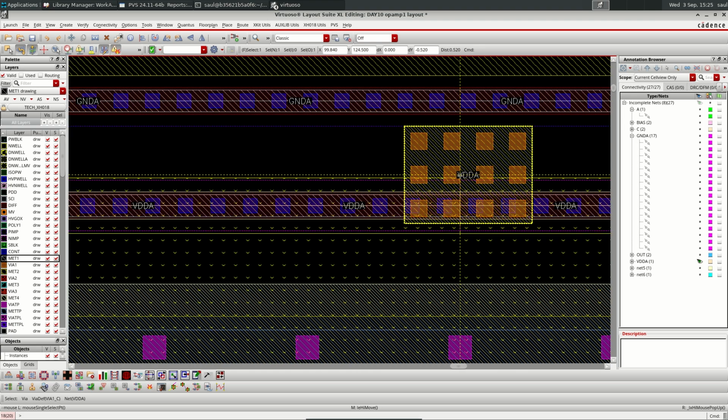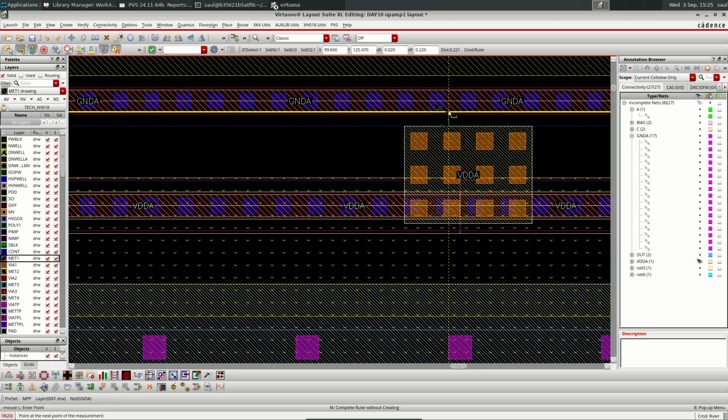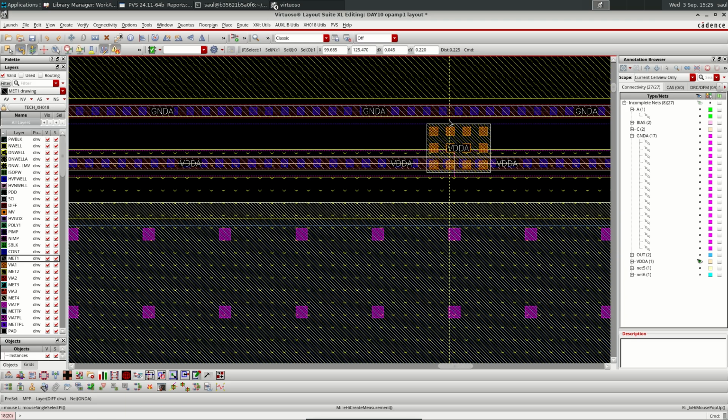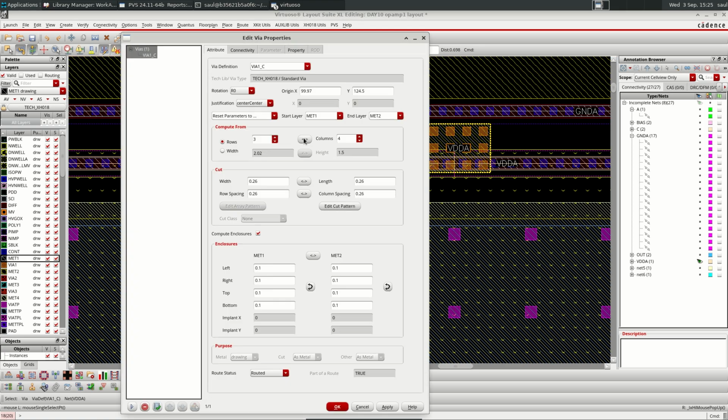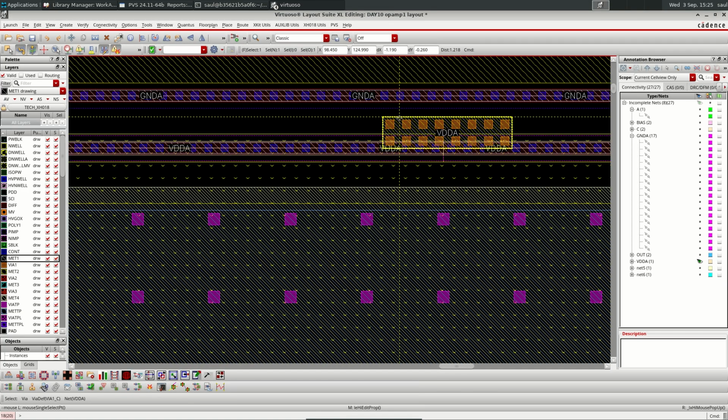That will make it. Spacing is going to draw on DRC. We're going to change to 2 rows. Apply, and let's make it a little bit longer, and that will make it. No, that will be okay.